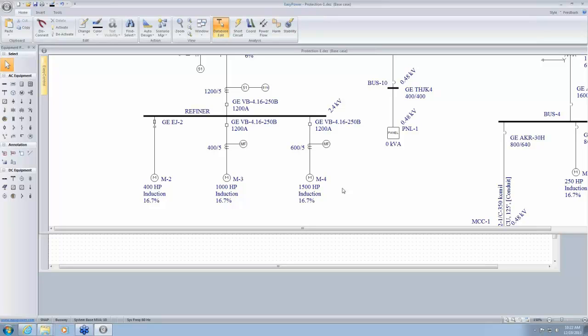And so that was the first talk about looking at bus orientation, or the orientation of the conductors with respect to how it affects workers and incident energies. Later on, there was another group of engineers that pointed out, if you have conductors that terminate on an insulating barrier, then the barrier tends to hold the arc, and it gives out much more incident energy than what a vertical configuration would give.